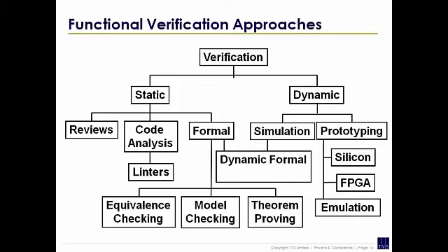Okay. So we're going to start looking more now on the static side. So we've looked at simulation. Static is where you don't execute the code. And you can do that by review. Okay, you can just do code reviews. Code reviews are a very good way of finding bugs. You've got static analysis tools as well. Static analysis tools like linters get used very, very heavily in software, less so in hardware. And we're going to talk about formal now. Formal verification.